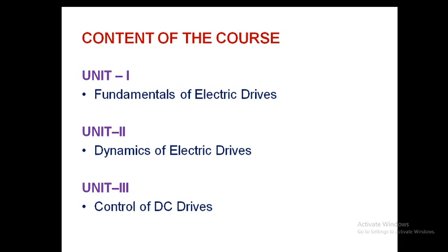There, that enters into the reverse motoring mode. Now from reverse motoring mode, again, if you reverse the speed, now the speed is in the negative direction. If you bring that speed into the positive direction, that is a reversal of speed, right? It will go to the fourth quadrant. That becomes the reverse braking. So these things we'll see by drawing the characteristics also. If you understand that fundamental torque equation, from there only we will draw the characteristics.